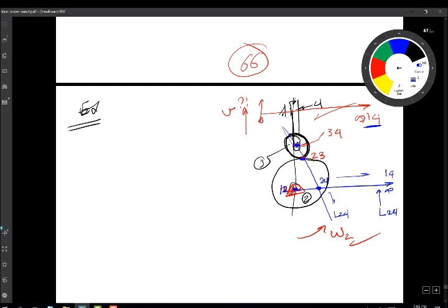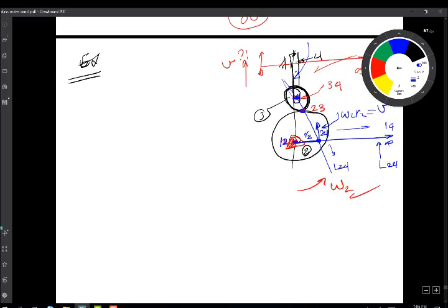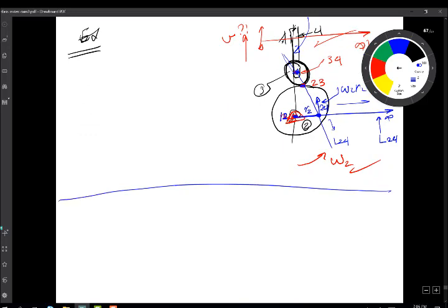So this falls on the cam, number 2, and on the follower up here, number 4. The common point is down here. So if I want the velocity of this point, I can call this R2, and I can say, okay, velocity here is equal to omega 2 R2. It is the same velocity of the follower because the point is called 2, 4. So it falls also on 4. So this is V of the follower. That's one example. Let's do another example.